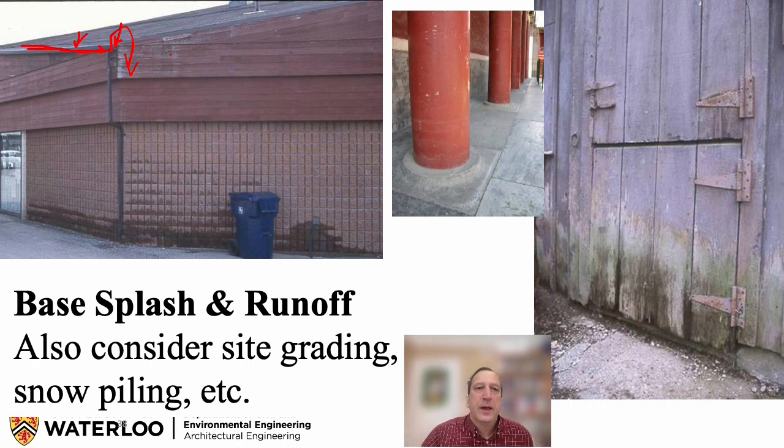Also, you'll notice here, even though the roof is exactly symmetrical, they've just chosen not to put an eaves trough, and the water just drools over the edge. And in all cases, you can see the lack of overhang and water management means the base of the wall is getting wet from splash and wicking up water from the asphalt parking lot.